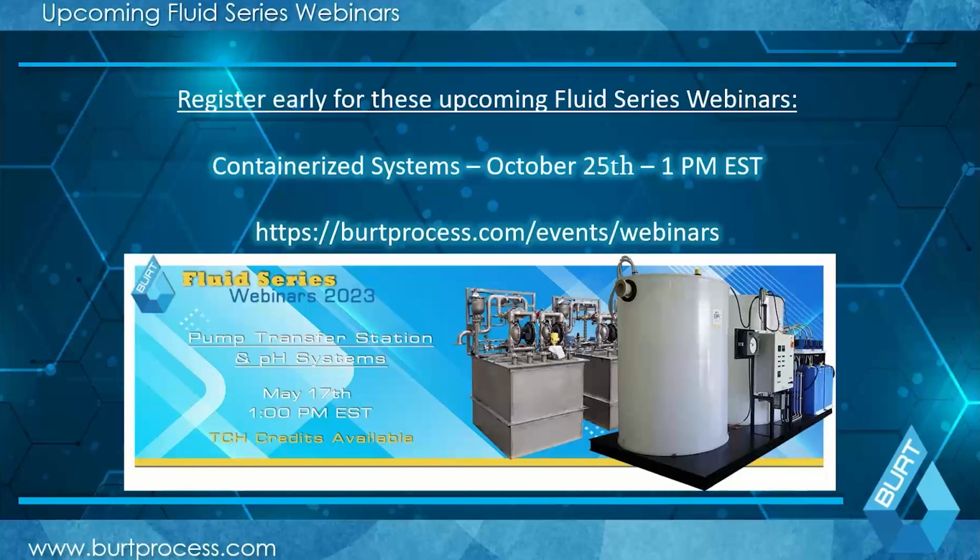That being said, if you have to be lower, you can get within about 3 or 4 inches of the bottom of the tank if needed. The only thing you have to do in that case is use a different style of pump. You need a self-priming pump, or an in-tank submersible pump, because your impeller has to be submerged to allow a lift station to operate. You can end up with a lift station that gets really short, and there is a geometric limit to how small you can make one, just based on getting a pump, a level control, and everything in there. That tends to be about 5 to 7 gallons. The problem is when you end up with a flow of, say, 15 GPM, that's a very small lift station, a very small volume.